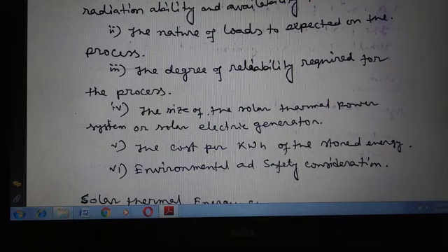In sensible heat storage, the temperature of the medium changes during charging and discharging of the storage. In latent heat storage, the temperature of the medium remains more or less constant since it undergoes a phase transformation, that is transition from solid to liquid or from liquid to vapor. Thermal energy is stored by heating, melting or vaporization of material, and the energy becomes available as heat.